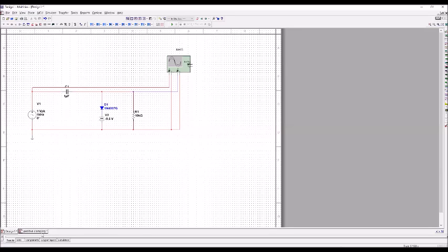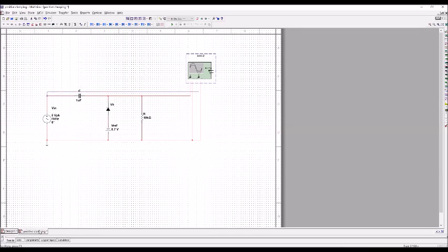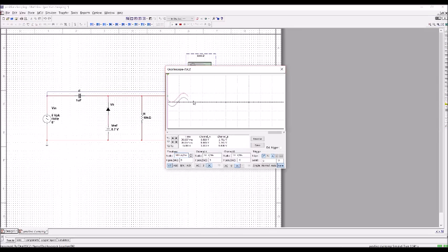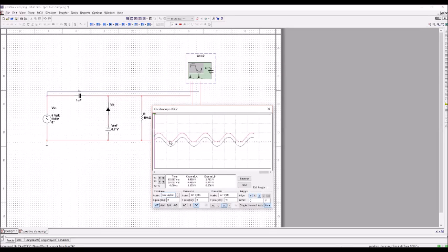We can design the same for a positive clamper, which pushes the waveform in the positive end towards the positive side. In this, the values of capacitor and resistor are the same. In this, we have used a diode which has a drop of 0.7. So when we see the output of this, in this case, blue is the input and red is the output.